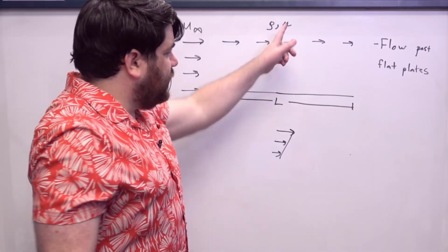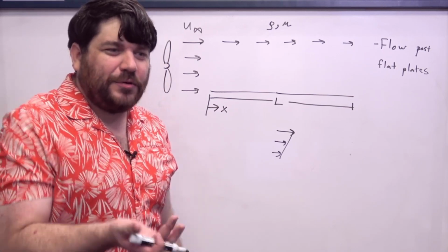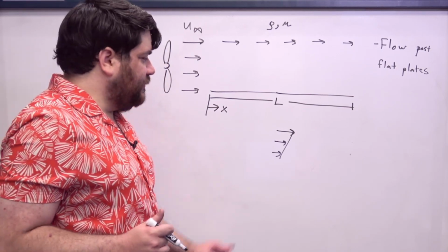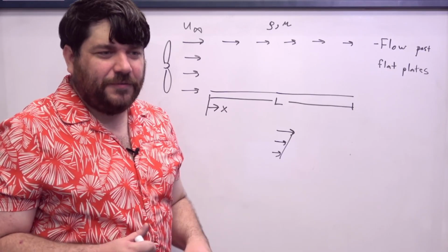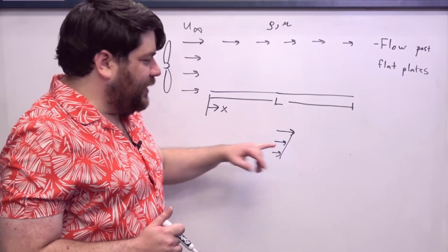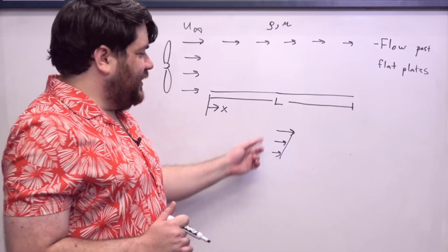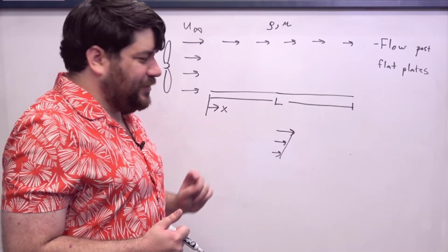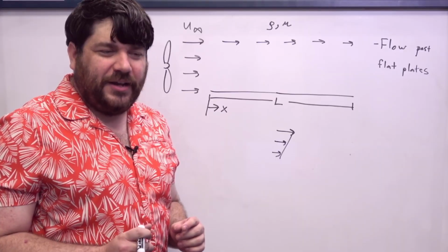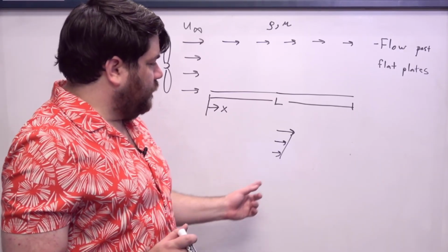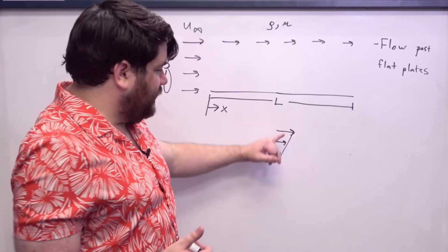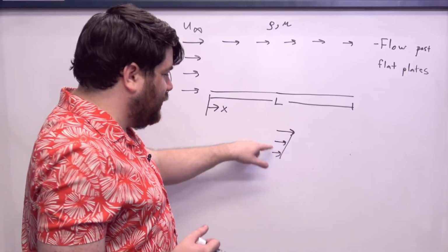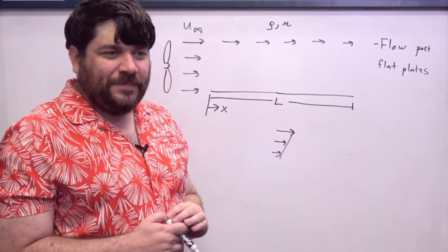All that you should know is that the viscosity is a proportionality factor that relates the frictional force per unit area that impacts a little piece of fluid that's next to another piece of fluid. It relates that force per unit area to the rate of change, or the gradient of that velocity, around a specific region of the flow.